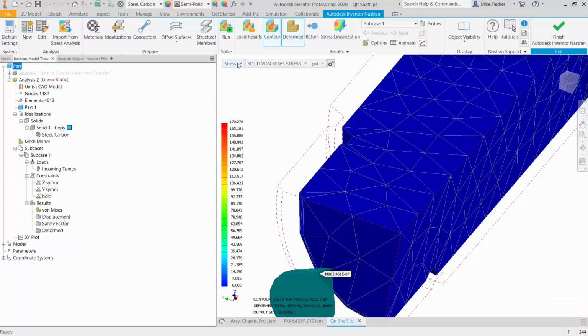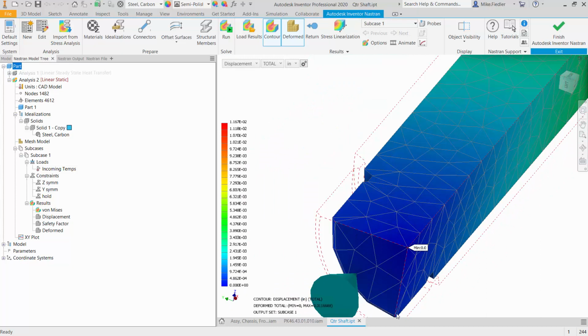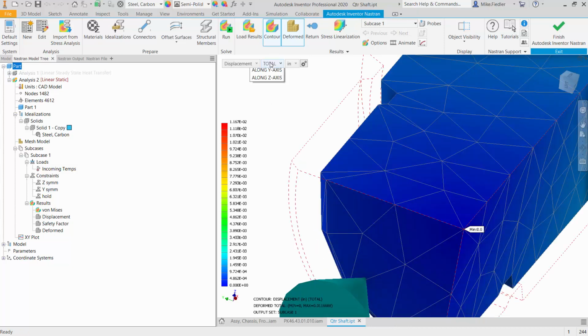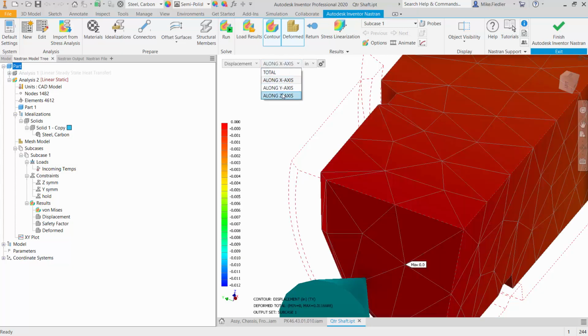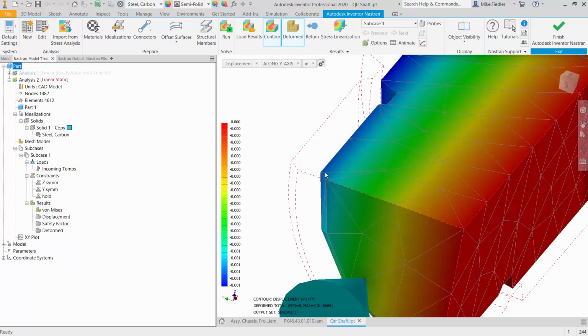So let's take a look at the displacements so that we can inquire on what that is. I can interrogate either this node here to find out how much it displaced along the y-axis, or I should find the same thing on the node on this axis, how much it contracted in the z direction. Either one of those should work. So let's take a look at, say, along the y-axis. I accidentally chose x. Let's say along y. There we go.